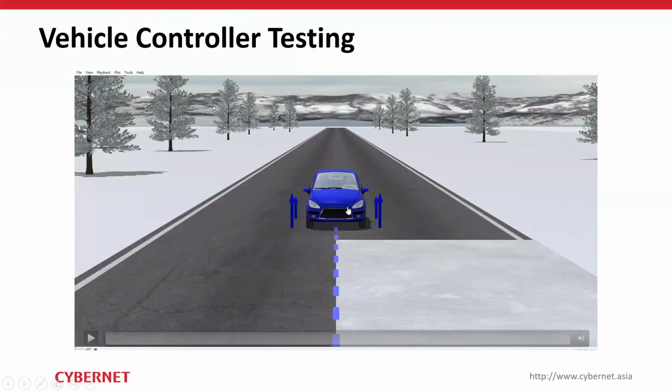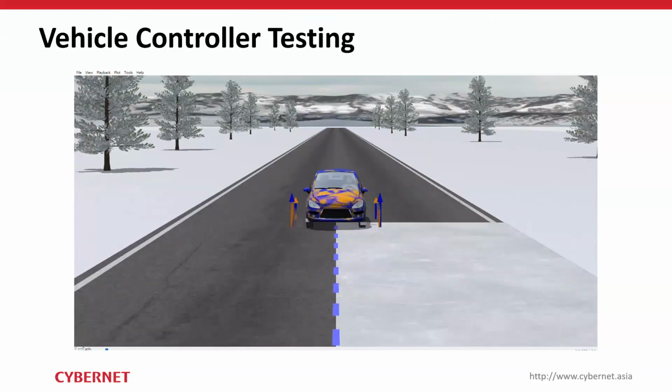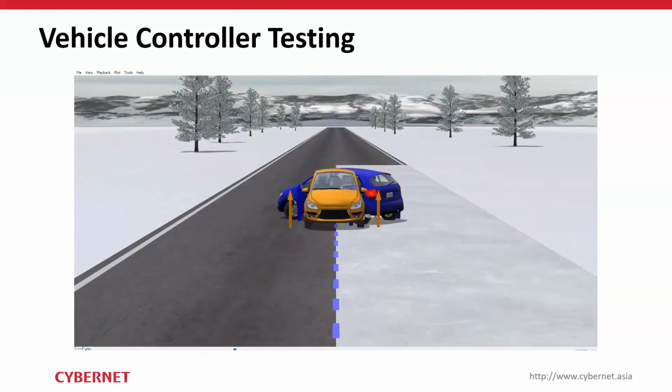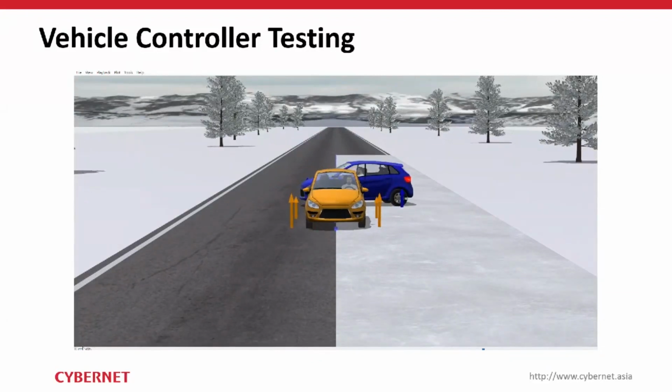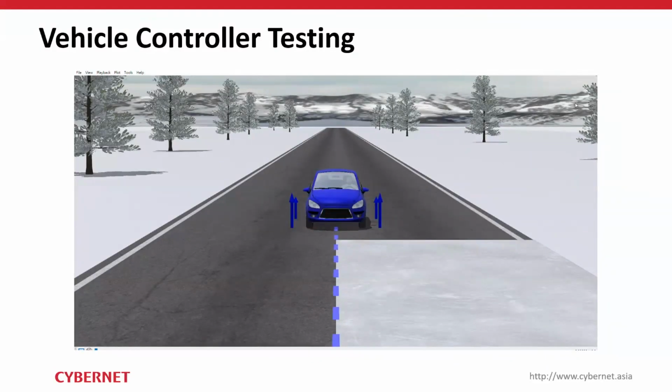As an example, the testing of an anti-lock braking system. We can overlay two kinds of simulation results, with or without the ABS controller on a split friction road. Testing and comparing with different kinds of models will be easier and cheaper in simulation. We can use these to develop and tune our controller at very low cost. This is how we build vehicle models and develop controllers with simulation tools. Much quicker and much safer.